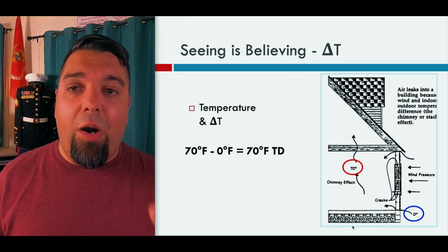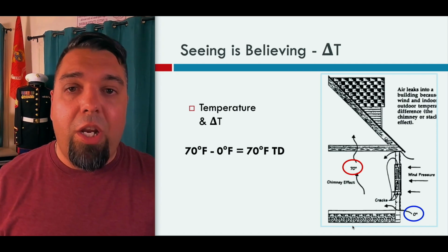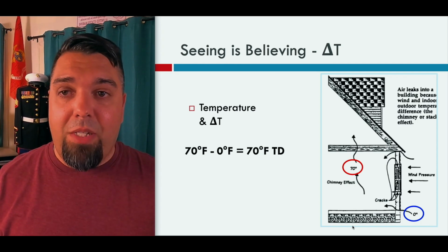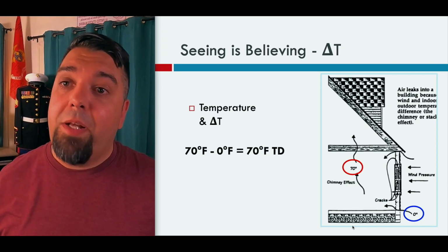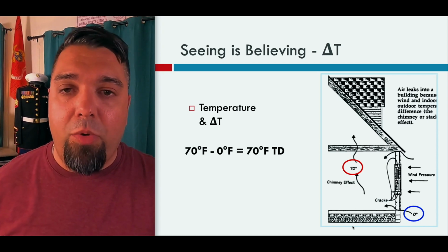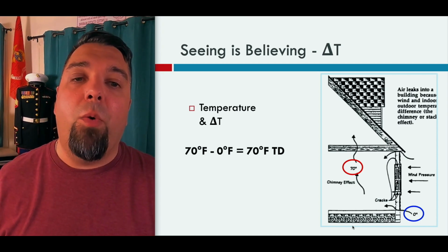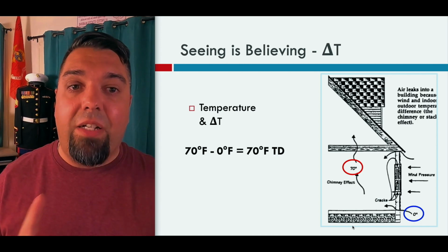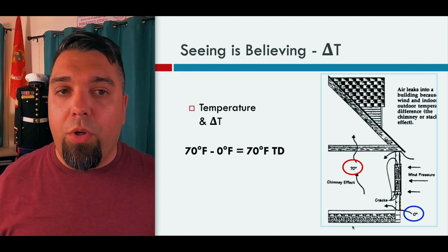And then, of course, your outdoor design conditions. Obviously, 0 here in the Northeast is a common number that's used. Doesn't mean it's correct. Sometimes it's 12, sometimes it's -5. Depends on where you're working. You should look that up in Manual J, version 8, tables 1A and 1B. All right? That would be your delta T across that wall, ceiling, floor, whatever it is to outside.